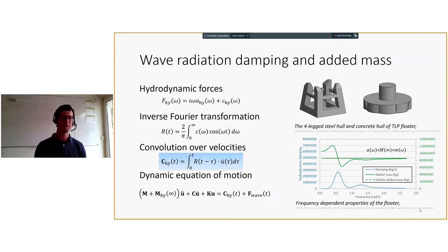The challenge here, as you see on the right hand side, is that these are frequency dependent forces. The hydrodynamic forces reflect as added mass and added damping. What we do here is a well-known procedure. We do a transformation into the time domain, and then we convolve this transformation over our velocity.